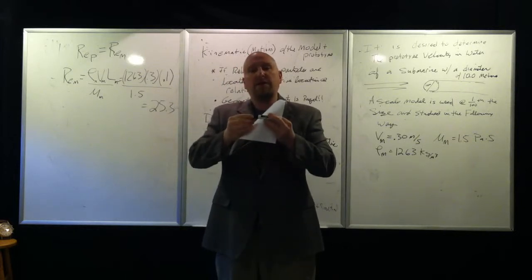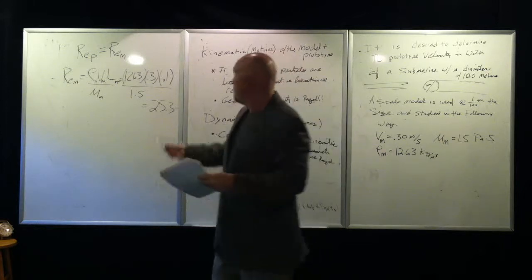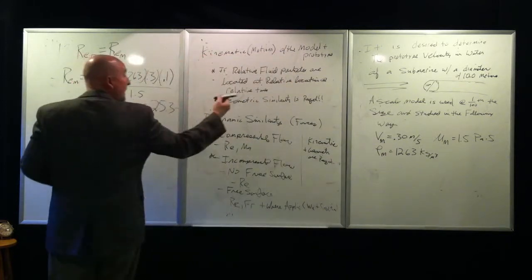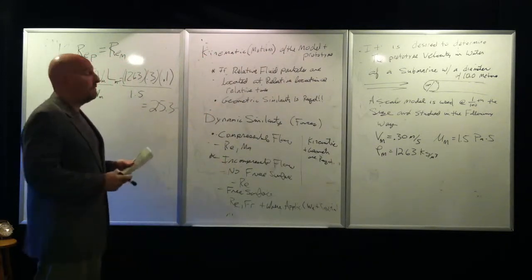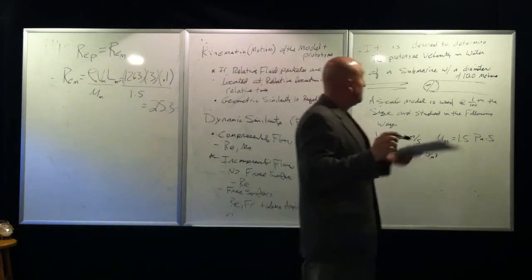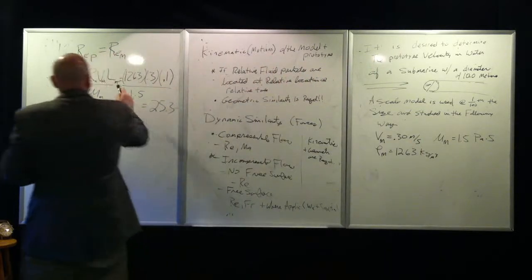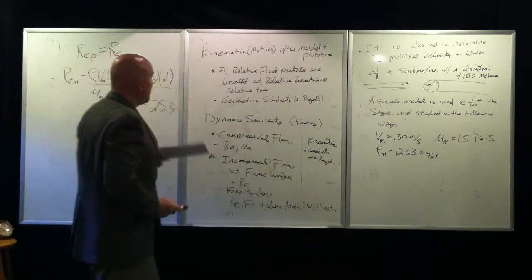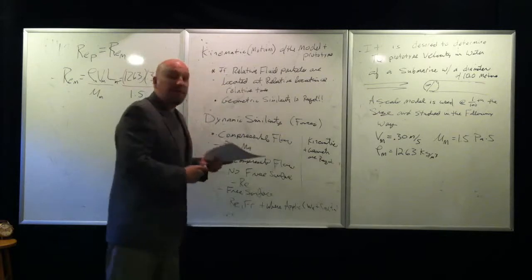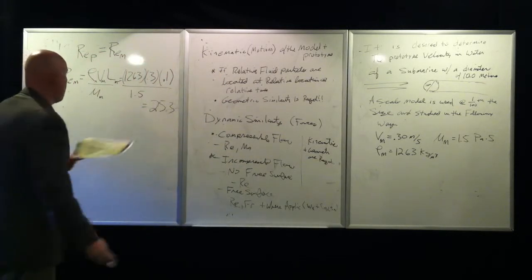Frontal diameter of your tiny model, that would be the Reynolds number that would be existing on this model, small, easy enough for a human to handle, and perform in a reasonable size space. Therefore, to have geometric and kinematic dynamic similarity, the Reynolds number of the prototype has to be 25.3.